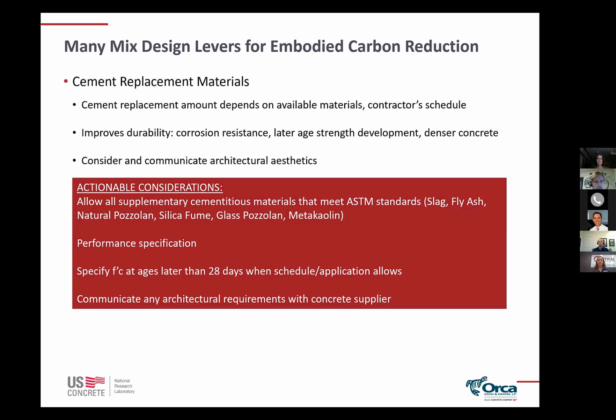So some actionable considerations are to allow all supplementary cementitious materials that meet an ASTM standard. Products like slag, fly ash, natural pozzolan, silica fume, glass pozzolan, metakaolin, those all have ASTM standards associated with them to guide the quality. And so the more of those that you allow, the more flexibility you're giving to a ready mix producer to be able to incorporate those, or for you to allow your project to go with whatever is available in the market. Then having a performance-based specification in this case is going to help.